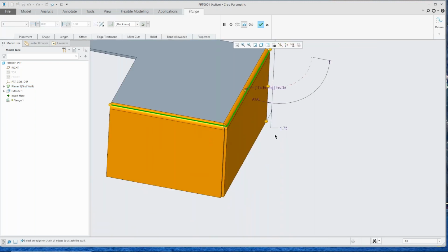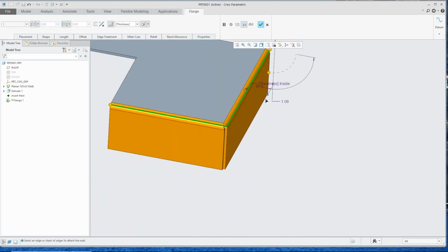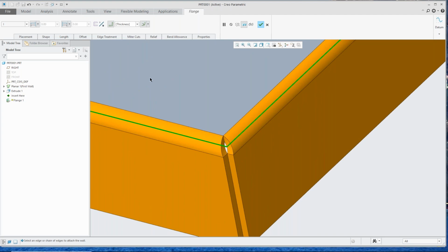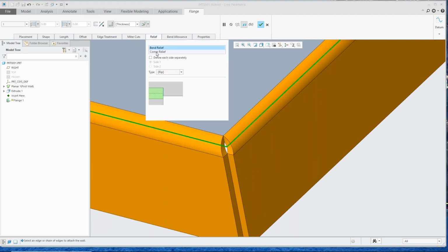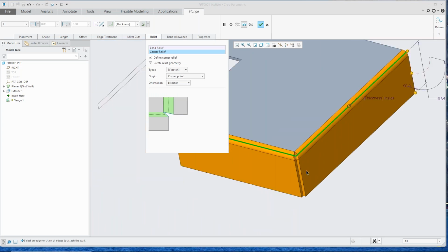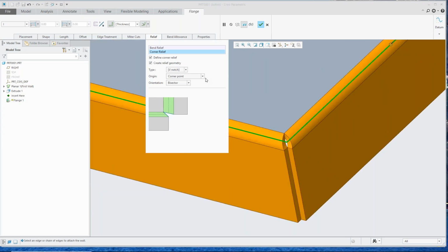family table, but here I want to create a rep. So by doing that, here's our rep name. We'll just take the default, and it flashes real quickly for us, but here's our master rep that we're looking at here. And if I go under reps, we can see here's our flattened version. I double click on it. We've got the flattened version. So the master rep is fully bent. So that's something new that's been added to Creo 5 for the sheet metal users.